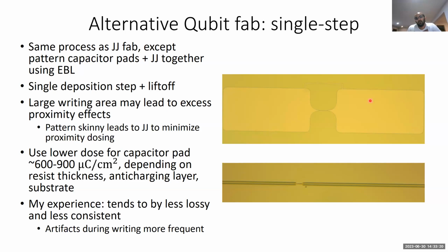Wire bonding. In our lab, we usually make 3D transmons. Those are floating transmons without a ground plane, so we don't actually do any wire bonding. But there are others in our group that do wire bonding for, say, parametric amplifiers and stuff like that. I believe the big precaution is to make sure you have one of those ESD bracelets, and make sure that you yourself are grounded and you're not generating any excess electrostatic discharge. And make sure your bonder is grounded as well.